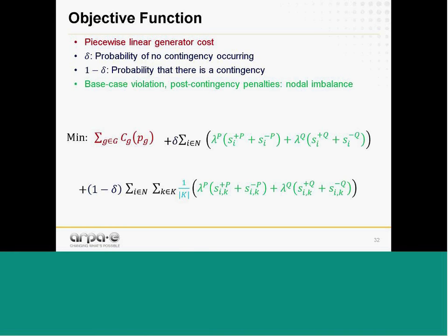You're going to have penalties. What this represents, again, is that if I don't satisfy flow in equals flow out, a very common network flow constraint, you're going to have a penalty. So if your real power is insufficient at that location or your reactive power is insufficient, you are going to get penalized. These penalty prices are going to come directly from ISO existing practices today that are in all of the market management systems, all of the market environments today. They vary based upon what prices they assign, but every entity has a limit basically on the LMP, locational marginal price. That's essentially driven through the node balance constraints, okay?